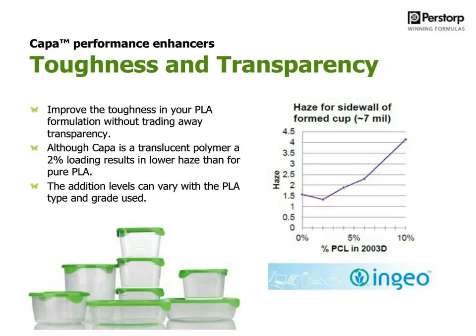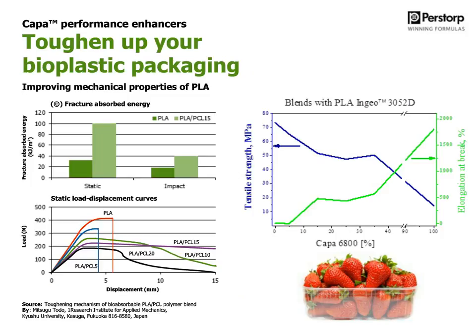Moving on to mechanical properties, PLA suffers from brittleness and cracking, and we have evaluated it. There have been several studies done where PCL has been added into PLA to see what it can contribute. Even at low levels of 5%, you can see a modification of the PLA. But we have also found that when working with these low addition levels, like 5% of PCL, there is always a degradation of the PLA in the compounding process.